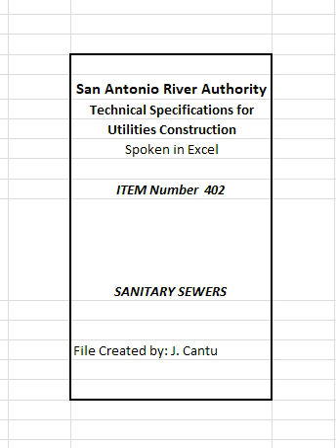D. Where a sewer crosses over a water line, all portions of the sewer within 9 feet of the water line shall be constructed of cast iron, ductile iron, or PVC pipe with a pressure rating of at least 150 psi using appropriate adapters. In lieu of this procedure, the new conveyance may be encased in a joint of 150 psi pressure class pipe at least 18 feet long and 2 nominal sizes larger than the new conveyance. The space around the carrier pipe shall be supported at 5 feet intervals with spacers or be filled to the spring line with washed sand. The encasement pipe should be centered on the crossing and both ends sealed with cement grout or manufactured seal.